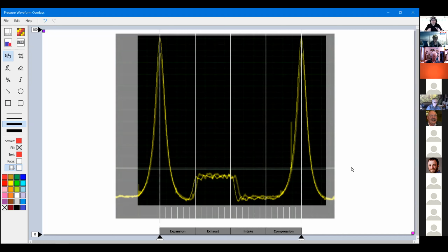I don't have to say, well, Adam, it's advanced by 30 degrees. I don't have to even get that carried away. Oh, I certainly would, but you don't have to. All I have to do is look at this and say, hey, boss, there ain't no spark plugs, injectors, throttle body, or computer in the world that's going to fix that fuel trim error, because mechanically one bank breathes differently than the other. You're done. That's it. It's out of mechanical time.